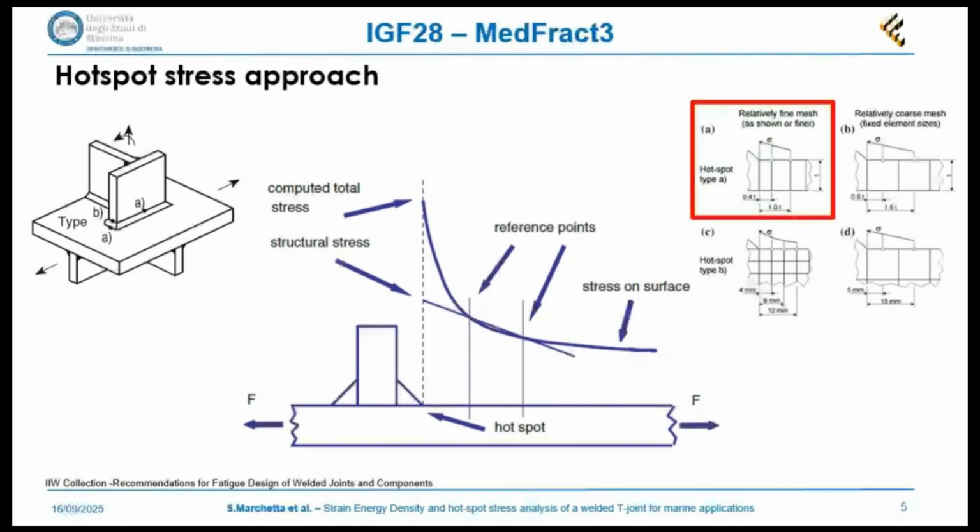The distance of the reference points with respect to the hotspot, with respect to the weld toe, strictly depends on what type of hotspot stress we want to extract and on the quality of the mesh of our finite element model.